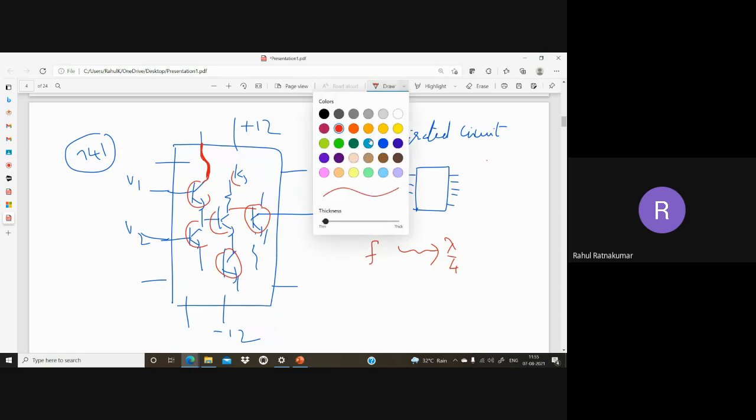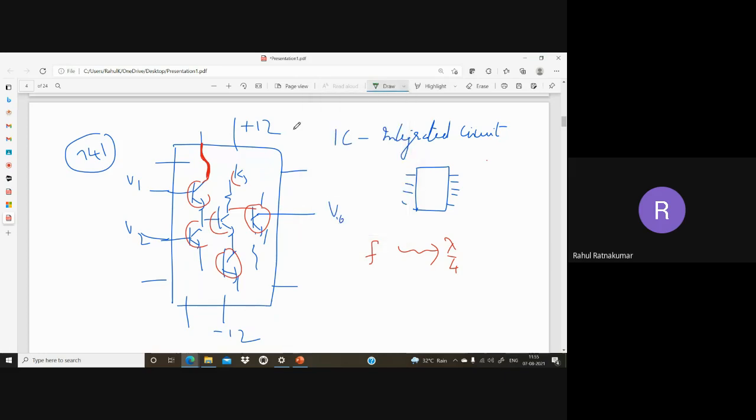There will be a lot of noise. Electromagnetic signals will be attacking them. We have a lot of frequencies around us: 5G, 4G, Wi-Fi, Bluetooth, different frequencies. So this will act as noise in your circuit, and it is directly proportional to the length of the wire. The wire acts as an absorption point for the radiation of different frequencies.